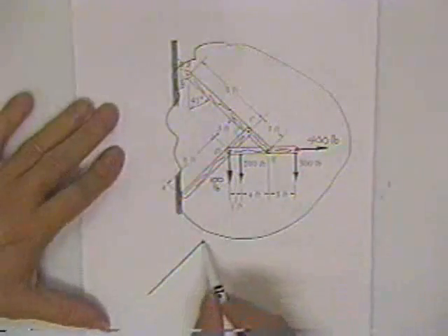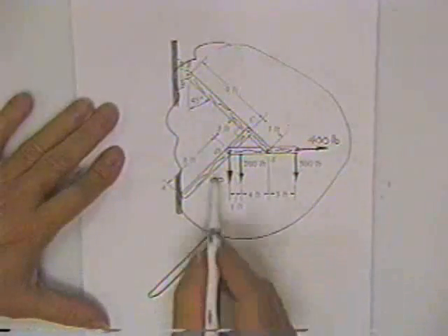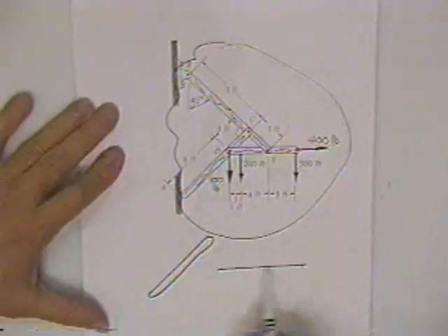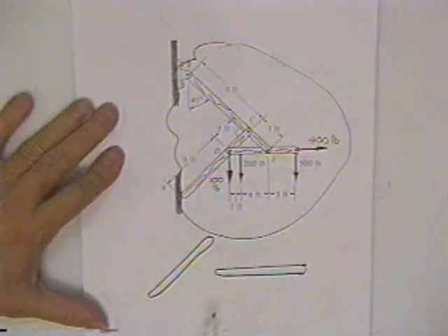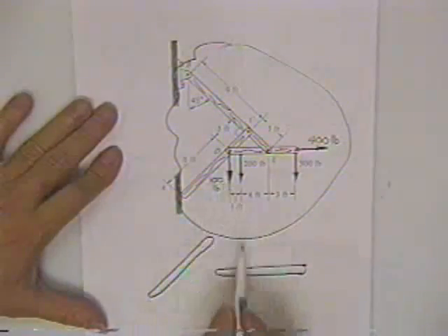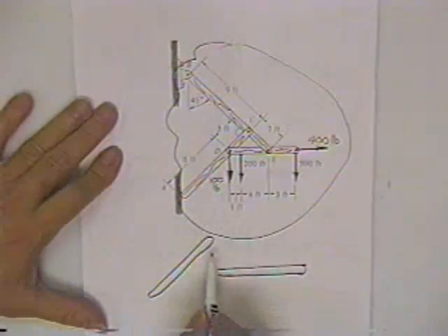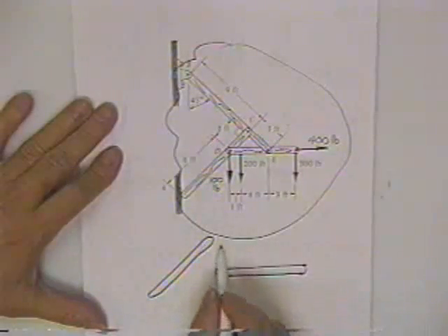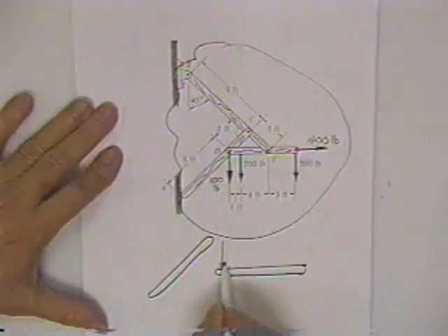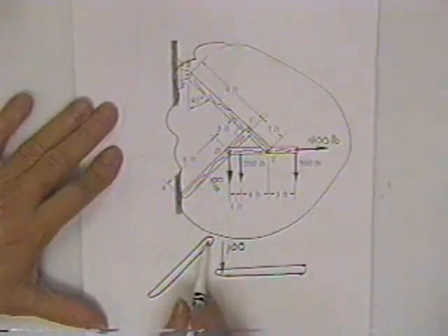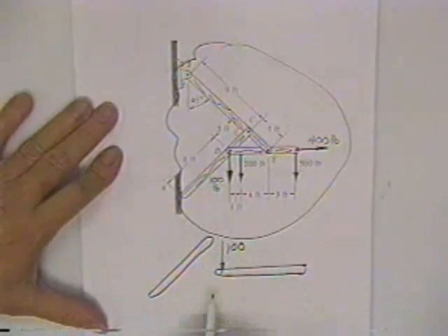But when you draw this free body, that's this one, and when you draw this free body, you gotta pick a place, just like a contractor. Contractor has to literally go put that 100-pound force on this member, or he's got to put it on that member. It doesn't make any difference. But if you put the 100 on this one, for heaven's sakes, don't also put the 100 on that one.